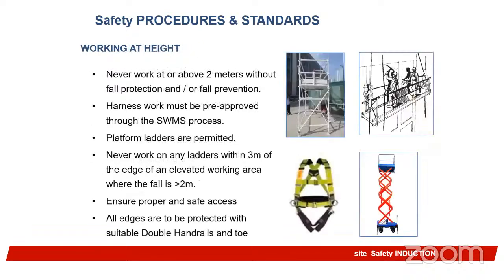Sorry. They talk about work at height. So part of your induction process, what you talk about during your induction. Anybody can work at height when it comes to certain activities. When it comes to working above 2 meters, in some organizations they say 1.8 meters, you must wear a body harness for protection or for prevention. The harness must be pre-approved through the safe work method statement. It is very, very important that you do this at all times.